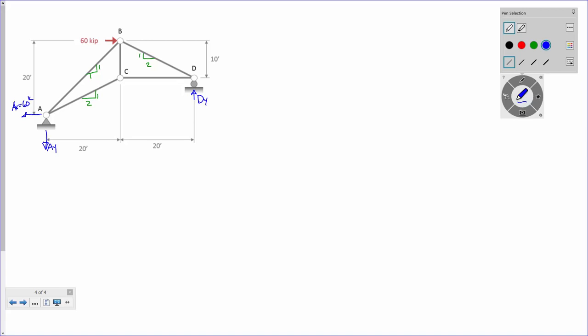Good? All right. So, what do y'all want to do? Some moments at what? A? Now, one thing to keep in mind before we start attacking this problem, in order to do deflections, we need the force in every member, which is why this truss is a lot smaller. So, do we have any problem using method of joints on this? No, this one's fine to use method of joints because it's such a small truss. So I'm going to sum moments at A. Use my little table.